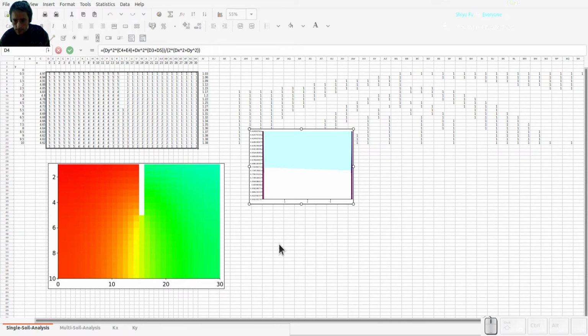And when we choose the style, we can define the axis color scheme. The scale setting again, minimum at 1. And we can change also the major ticks, say 0.5 or 0.2.